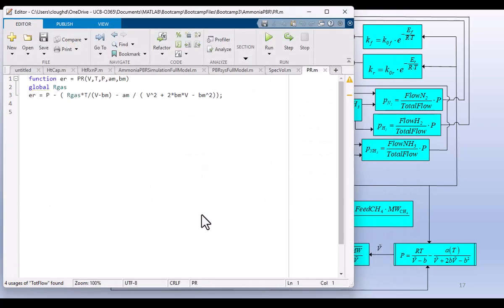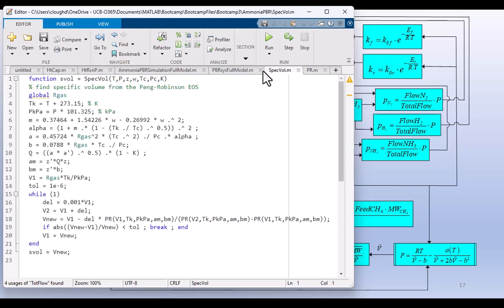this is fairly short, but what it does is it computes for us the Peng-Robinson equation set equal to 0, which we will achieve 0 when we have the correct value of the specific volume. And remember, I mentioned a correction on the slide of a v tilde going to a v tilde squared, and that's shown here where you've got the v squared. And I will correct that on the slide. So that comes back, gets us the specific volume.